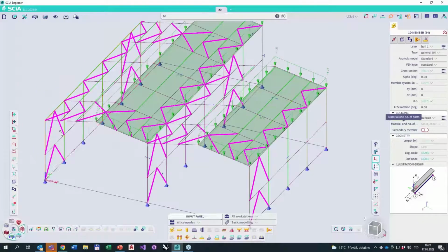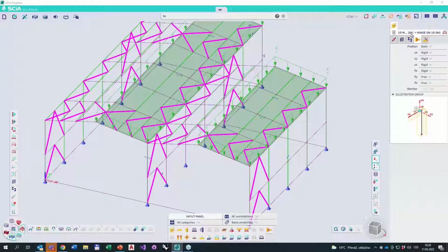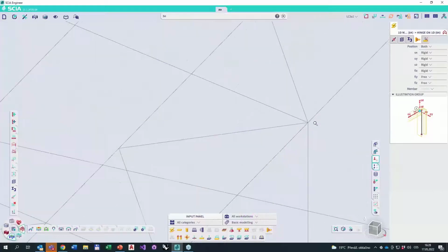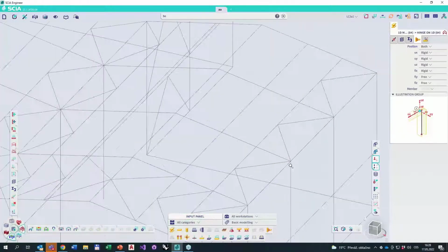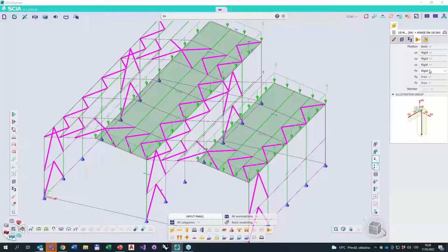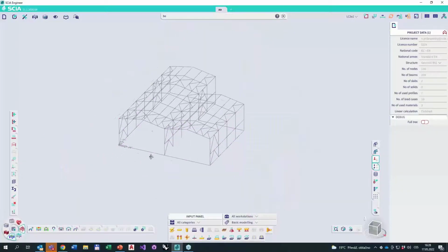So this way you can see I very quickly selected all the beams that actually have any of these three cross sections. What I mentioned also before is that now if I have my beams selected, I can actually go to hinges, because you don't even see hinges on these beams. But I can assure you there are hinges on them, and even though I can't see them, I'm able to interact with their settings because the hinges are a direct reference to the beams. So are, for example, layers, cross sections, beam nonlinearities, or you can imagine a lot of different data.